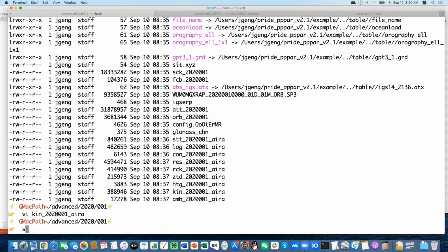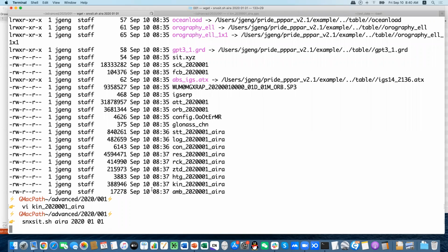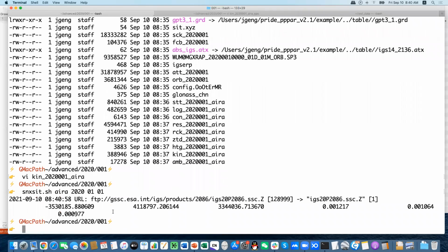All right. So then let's compare their precisions. We wanted to compare our coordinates with the IGS solutions because that makes things more objective. So how can we find the IGS solution for this station? ARRA. So I told you the command to look for the IGS solution, the weekly solutions, the truth benchmark. So 2020 and 0101. So let's see how IGS computed the result. So this is the IGS solution coordinates, right? The correct one, or the truth benchmark. So we compare our coordinates with this.